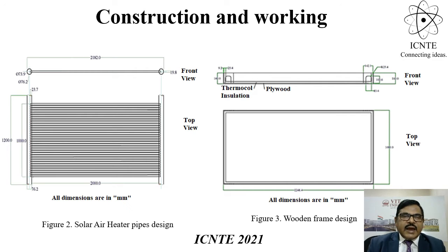You can see in this slide the construction and working. Here there are two headers, top header and bottom header, and these two headers are connected by small pipes. You can see these are all small pipes. The small pipes are attached to both the headers, and these are all plastic, and they are welded to the top header and bottom header so that air will not leak.